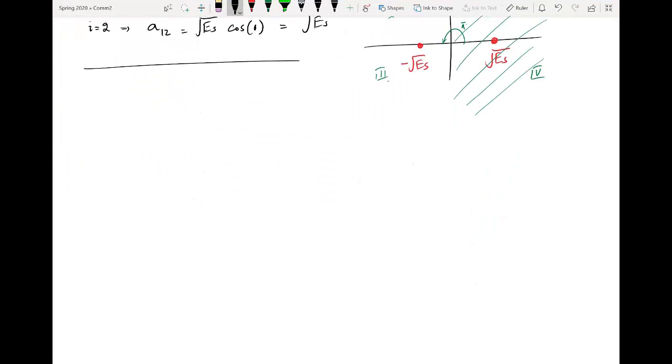For M equal to 4, if you find out the angles, the angle is phi_i equal to 2 pi i over capital M. You see, for M equal to 4, they will also be placed maximally far apart from each other, because if you divide 360 degrees into 4 parts, each will have 90 degrees. So each decision region will contain 90 degrees of the entire plane.